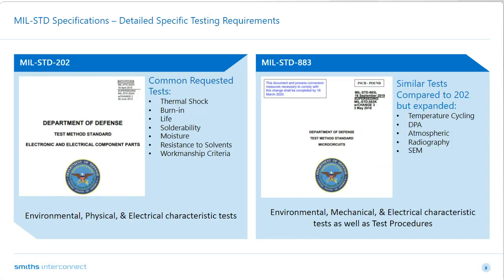And here's a quick look at MIL-STD-202 and MIL-STD-883. So again, MIL-STD-202: thermal shock, burn-in, life test, solderability, moisture testing, resistance to solvents. Those are just some of the very common tests required for our board level components and what is requested from a lot of our customers.